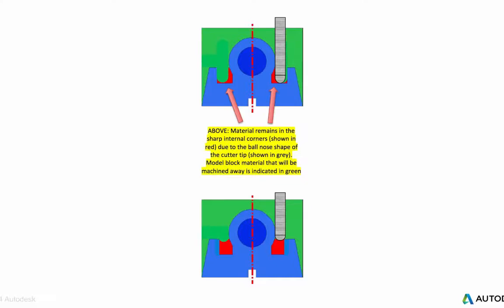These would be additional machining processes, increasing the complexity, time, and cost to machining the design. Note that with this design, there are still areas shown in red that the cutter cannot access. These areas are not possible to machine using any orientation.